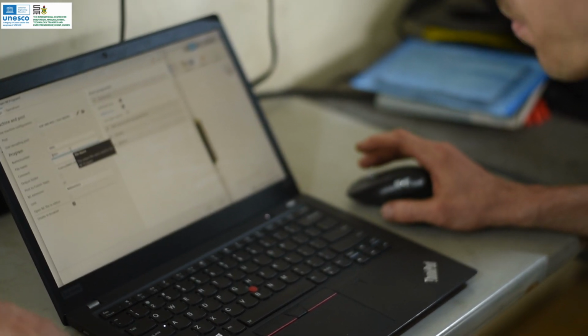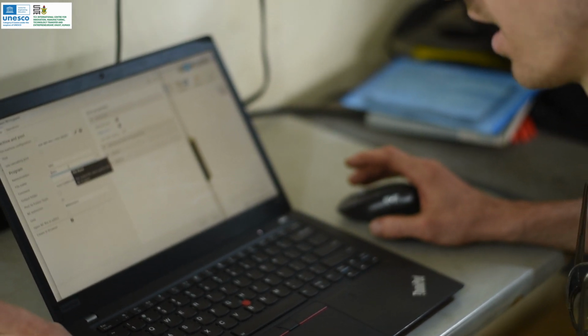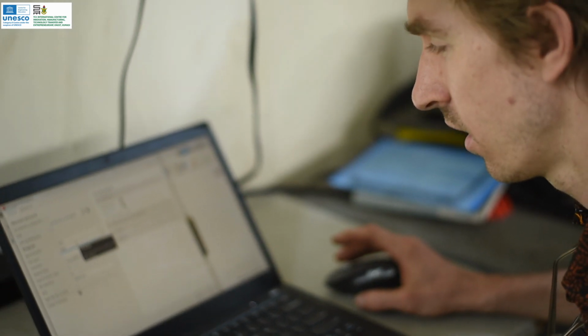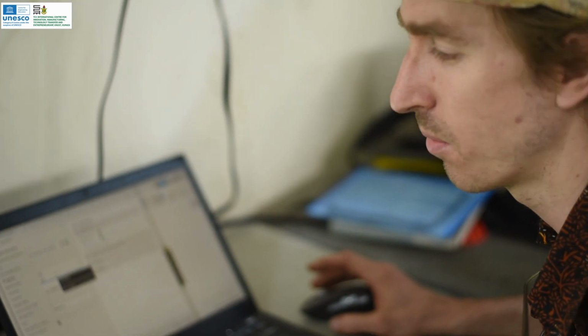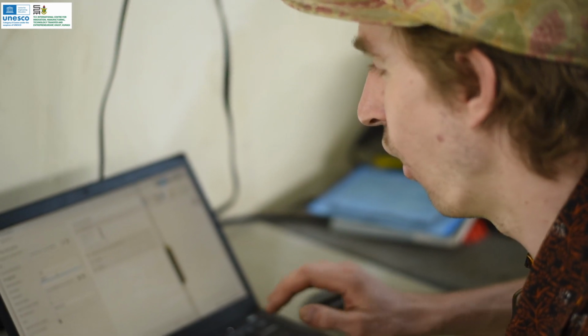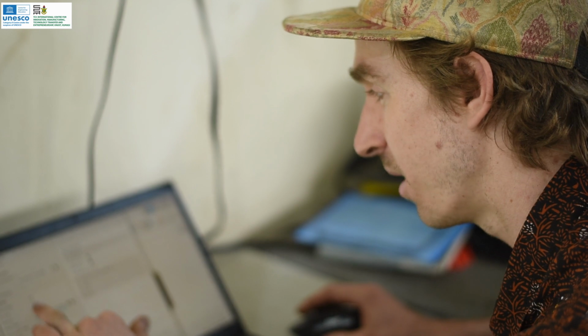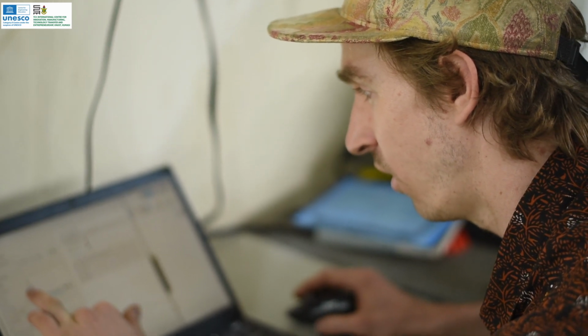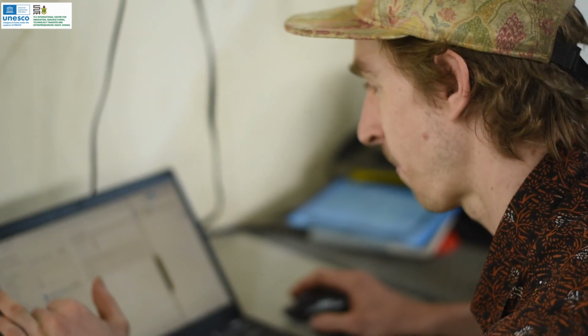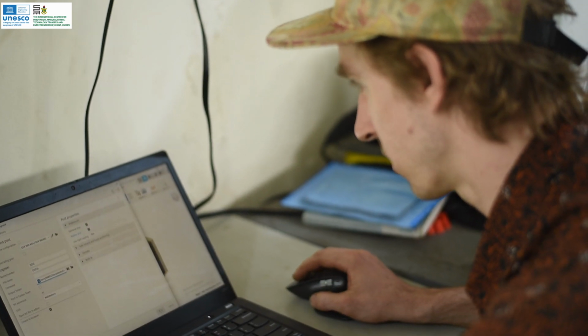And here's the trickiest part that took us the longest to figure out. All the files that worked looked like it was a 5-digit number starting in 0. In fact, it's a 5-digit name starting with an O, a capital O, and the letter O, not the number 0. If you put a number 0, it will not show up. And that's something that we struggled with for a long time. So just make sure that the file name starts with letter O and then 4 numbers. That's the only way it shows up.